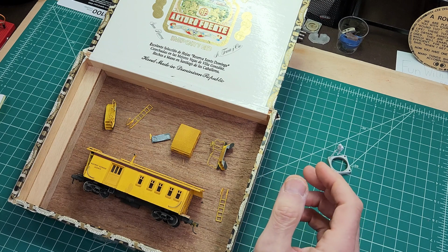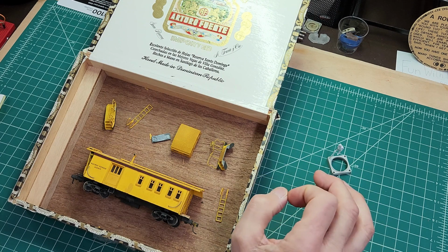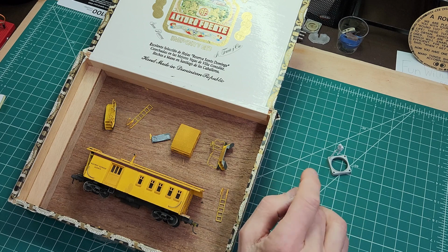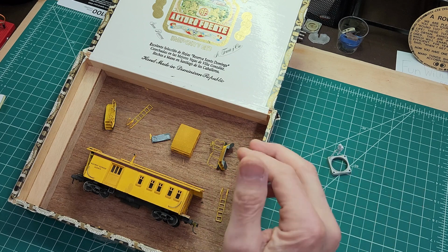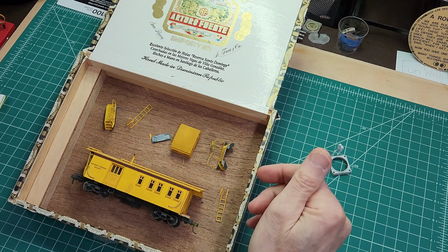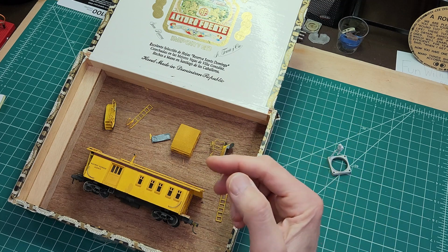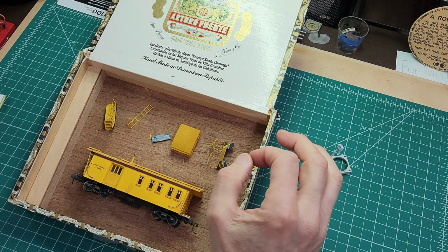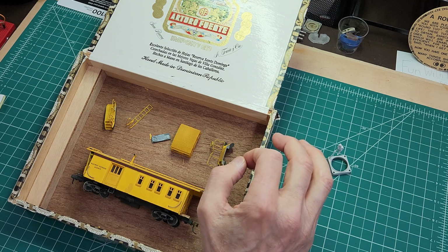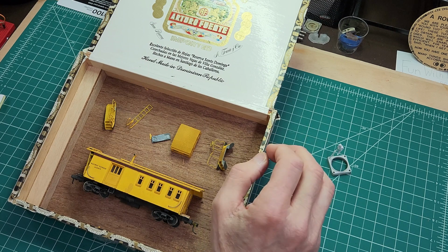The library performs next a configuration step that calls my driver's init method. The driver's init assigns a device number to the attached device. Now recall that the hub model requires that every USB device has to have a device number to distinguish it from others that may also be attached. Init next calls the library's GETCONFDESCR, or perhaps phonetically, get configuration descriptor method.